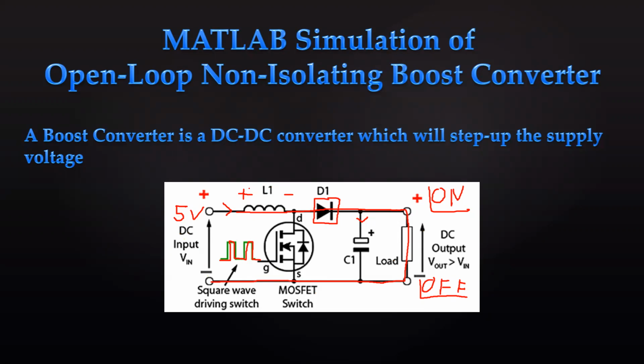So now what will happen? Earlier the inductor polarity was plus and minus, but now the polarity will be opposite. As we know, if this polarity is opposite, this whole thing will behave as a battery. Here we have plus and minus, and here we have plus and minus. So we can say that we have connected two batteries in series. If we connect two batteries in series, our current will be constant, but the voltage will add up. So the final output voltage will be 5 volts plus the voltage of this inductor. That is the increased voltage, right?